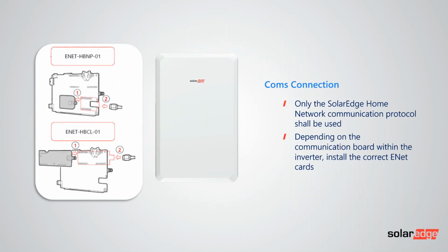What you cannot do is put the big one onto the board which has the 2 ports on it. The reason being is that it wasn't designed for it, and the battery terminal is much larger and it can cause communication issues with that board. Now this is only really a problem for existing installs which were put in over 2 years ago. All current inverters since then have the dual boards, so they'll take the small EnergyNet cards. So all new installs, this isn't going to be an issue at all. If you're going to add a battery onto an existing install, the advice is basically just to take both sets of cards with you, and that way you know to install the appropriate one.